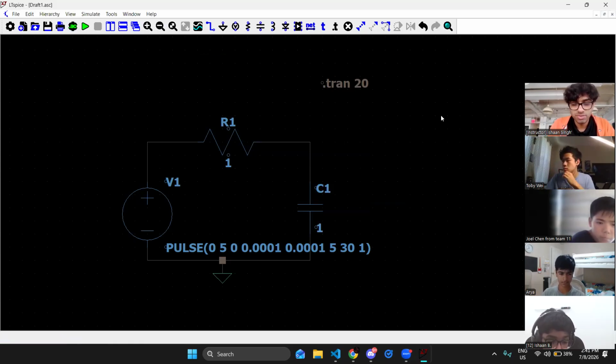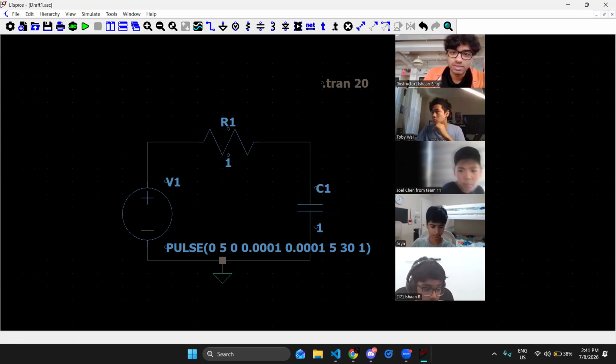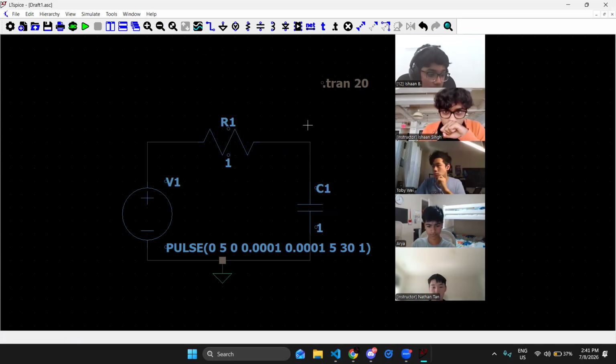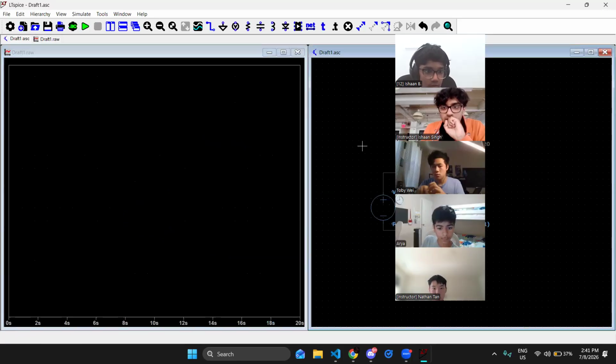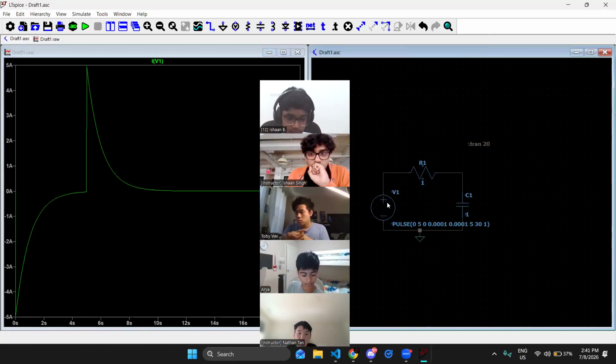Okay, so can someone tell me what they expect to see here? When I plot the voltage of the capacitor, what do we expect to see? Yeah, Ishan? So initially it'll be approaching 5, but it'll probably cut short of 5. If I did the calculation, it would go almost to 5, but it wouldn't reach 5, and then it would start going back down after the pulse ends. It would go down in an exponential curve. Right, exactly. I'm going to first plot the